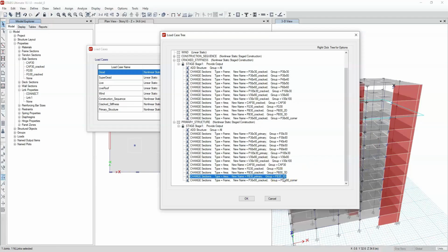The objective of this is to avoid strange problems or modes with very low frequencies in the modal analyses that would cause issues in the model. The idea is that with this model, using section modifiers, the primary structure works and resists the earthquake in shear and bending with 50% of its stiffness, while the secondary structure is almost non-existent in terms of strength and transfer of internal forces.